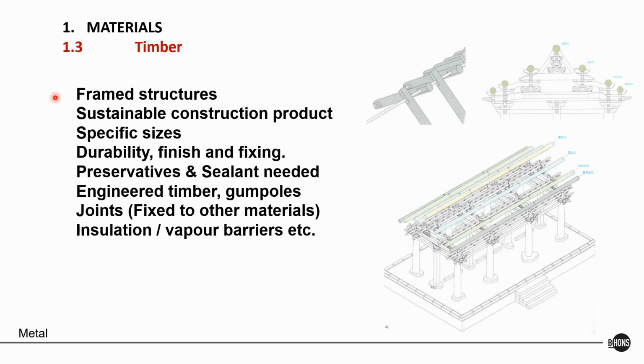Then remember, similarly to steel, and unlike concrete, which is very flexible, timber also comes in specific sizes, and you can go and have a look at it. I know the Architective has a lovely little table that shows all the sizes, but it's typically a 38 or 50 depth, and then a 38, 50, 76, 114 or 228 size in terms of the plank. It's important to understand those sizes, and if they get planed, they're actually a little bit smaller as well.